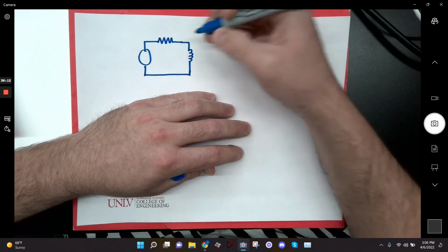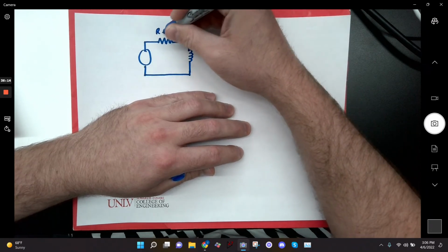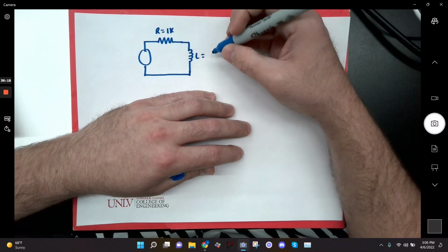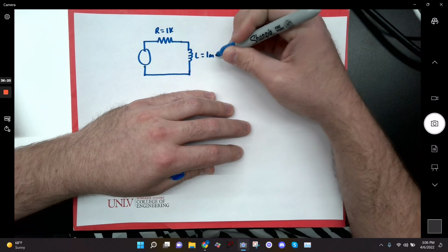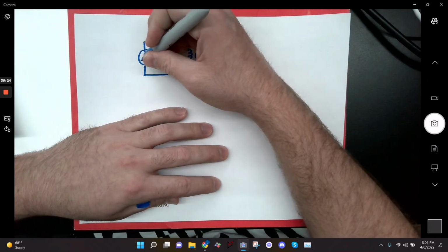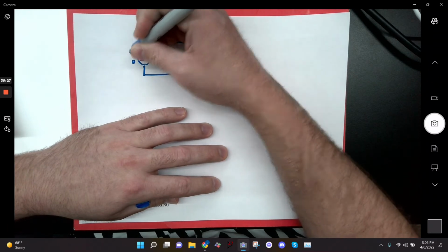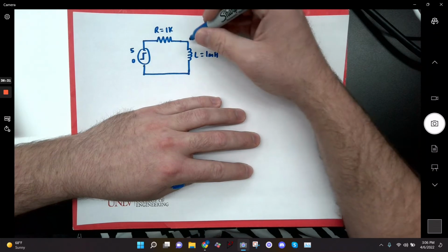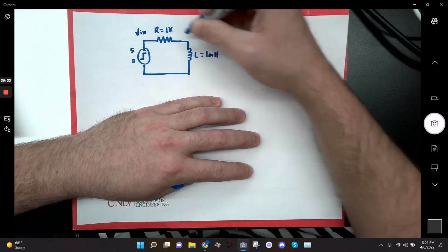All right. Got my R. Let's give it 1K, and then my inductor. Let's make it 1 milli. And let's say I want to start at 0 and pulse it up to 5. Then we'll call this V in, we'll call this V out.